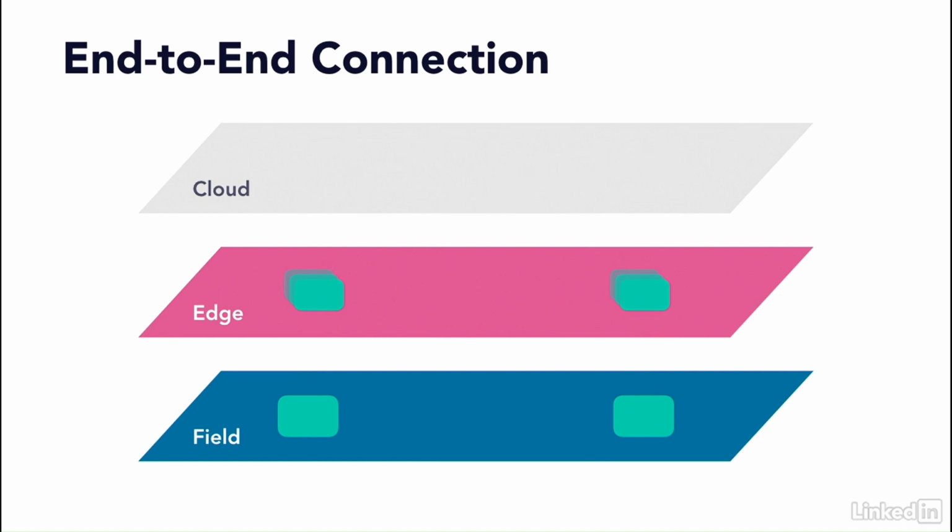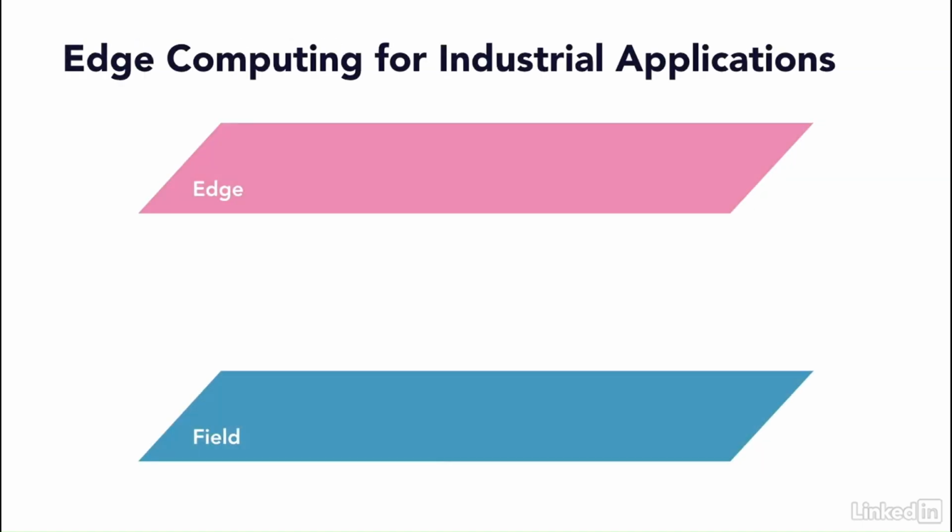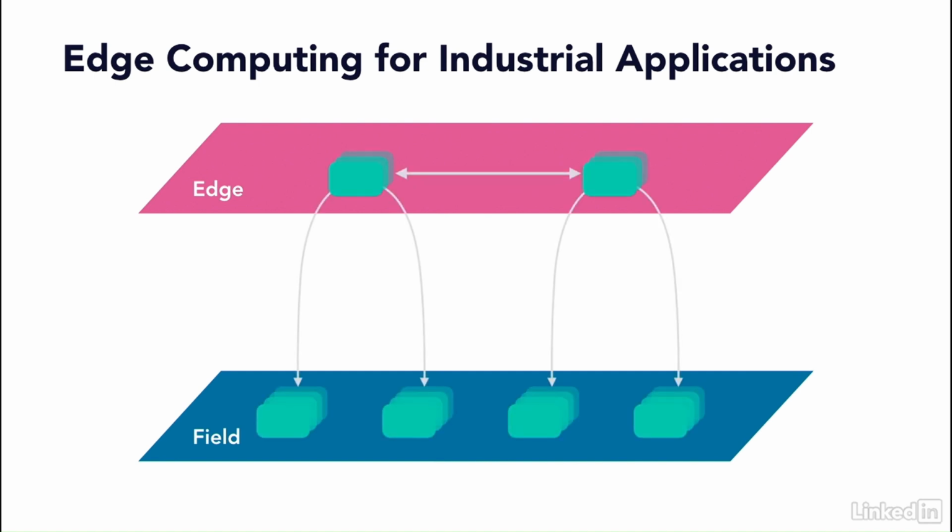A typical edge device mainly does two things: data and control. It collects data from field devices, processes and optimizes it before transferring it out to other internal or external networks. For some networks generating a big amount of data from field devices, for example, an industrial network with sensors for monitoring a production line, edge computing can help with doing some computing jobs based on the monitoring data received, and reduce the network traffic and make it more responsive and real-time.